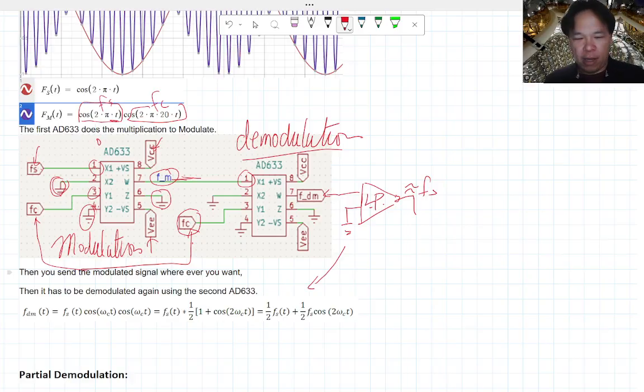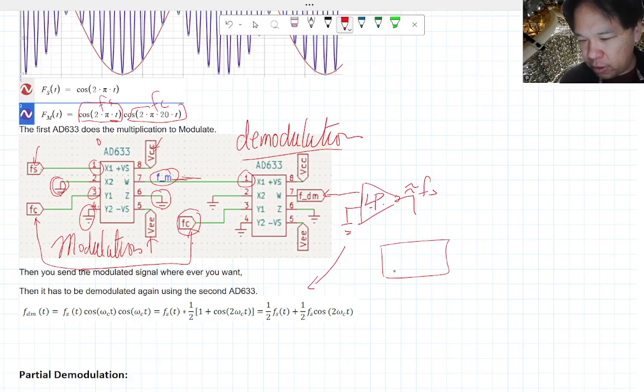And in the lab, I'll have you play around with that to see how much a slight difference in frequency and phase actually degrades your signal. But in the lab, since you're on just one breadboard, you can do that. One thing to note is that the way you would want to do this is that on your function generator, you want to split the signal right at the function generator and make these two cables the same length.